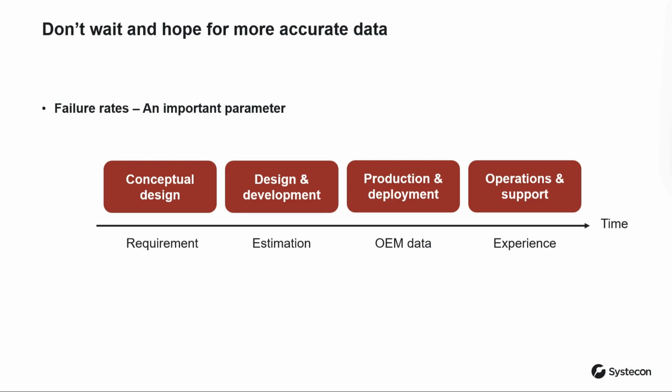The outcome is influenced by factors such as infant mortality, especially for newly developed components. The failure rates depend on the conditions in which the systems are operating, and after a while, one can expect the failure tendency to increase due to wear out. What I'm trying to say is that this parameter will never be accurate, so don't wait and hope for accurate data.